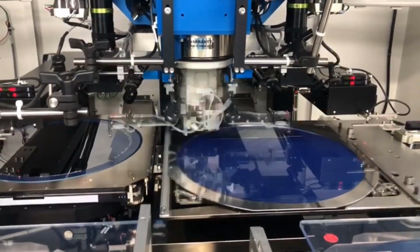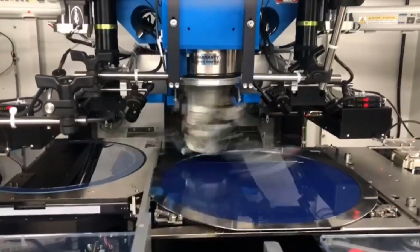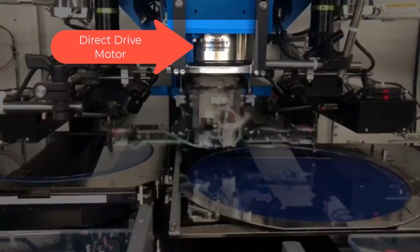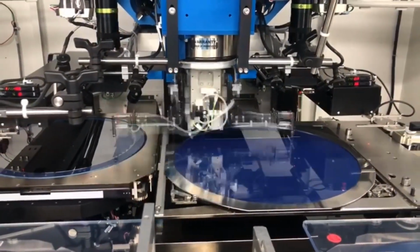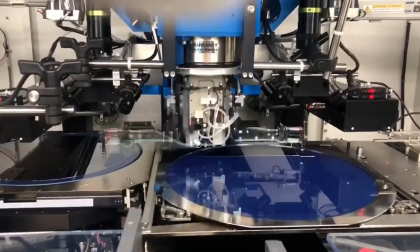This machine relies on high-speed rotary positioning of a gripper to handle small parts. It's easy to see the direct drive motor here on this machine and the simple mounting design. Since there was no backlash, the positioning was made repeatable on this small load with a settling time lower than 5 milliseconds. Additionally, the hollow bore design provided space for all vacuum tubes and wires to pass through the motor mount.